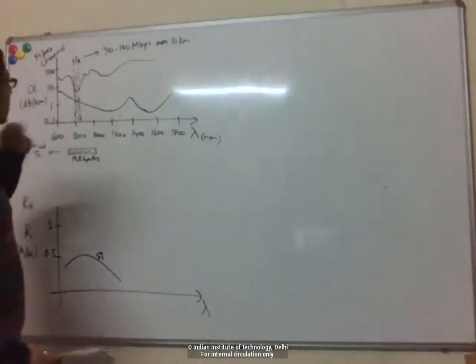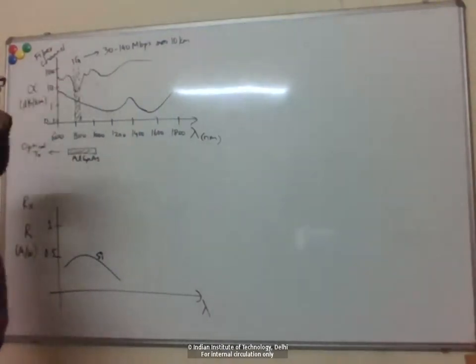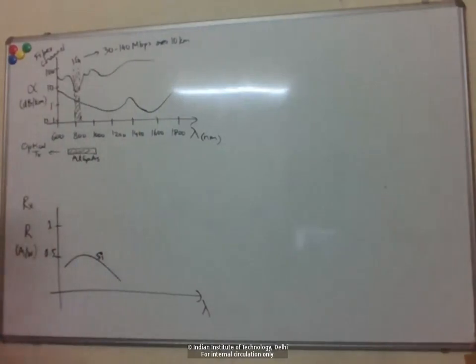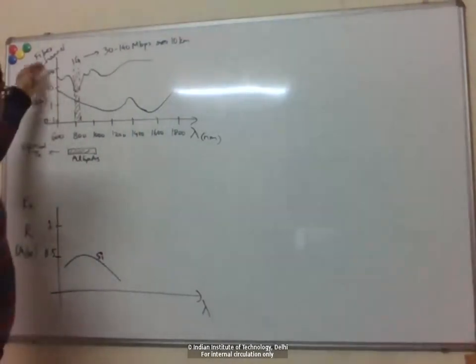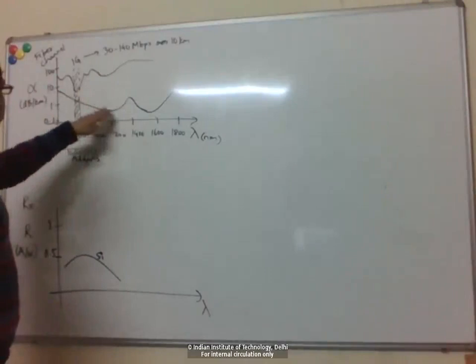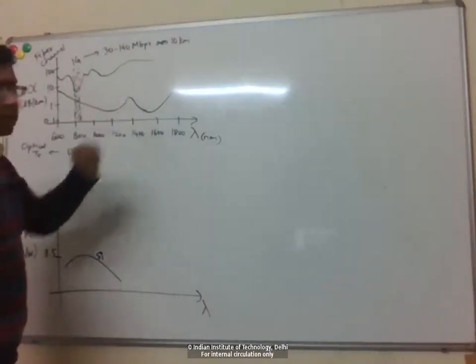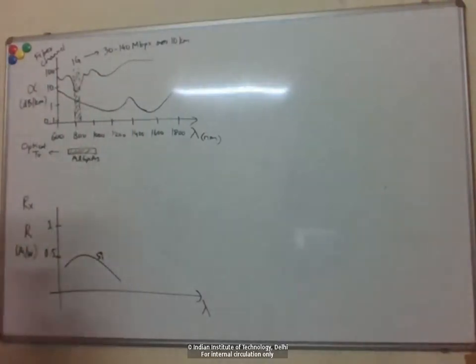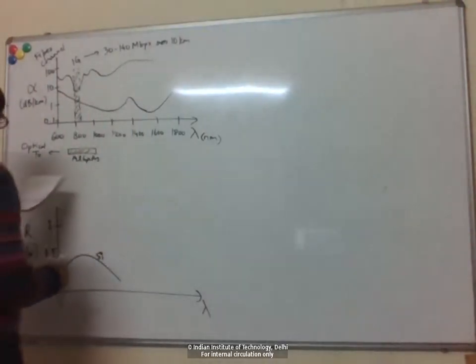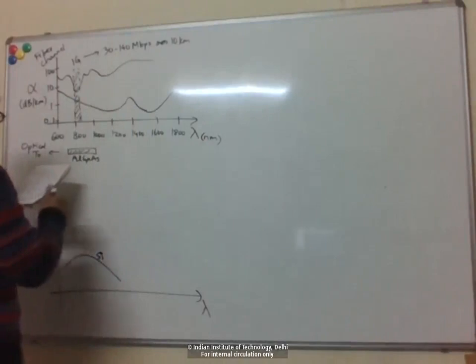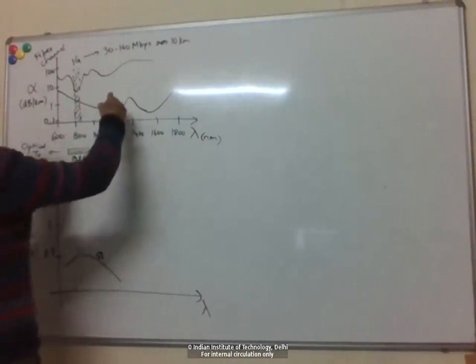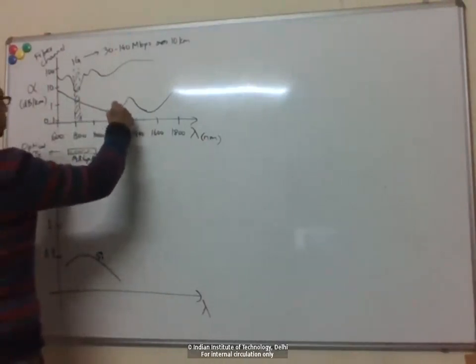The second generation of optical fibers were much better. Overall the loss was much lower, and the minimum loss wavelength now moved towards infrared wavelengths. This minimum occurred around 1300 here.